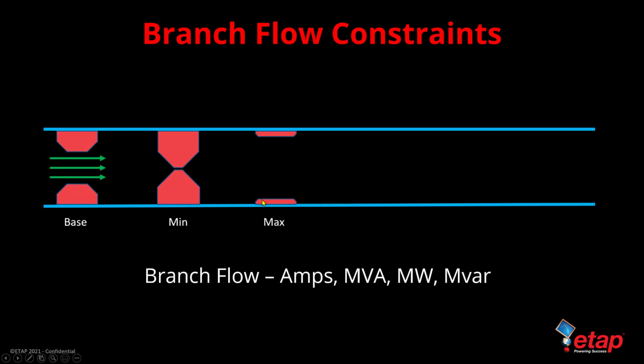We can then also define a maximum flow constraint, which is equal to a certain capacity of the line or a cable, such that we keep a certain amount of reserve and we don't reach the entire capacity of the branch or line. This is done to make sure that we have certain spinning reserve available in the system and or derating in terms of ambient conditions.